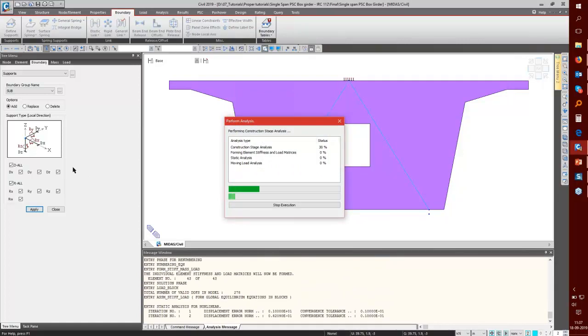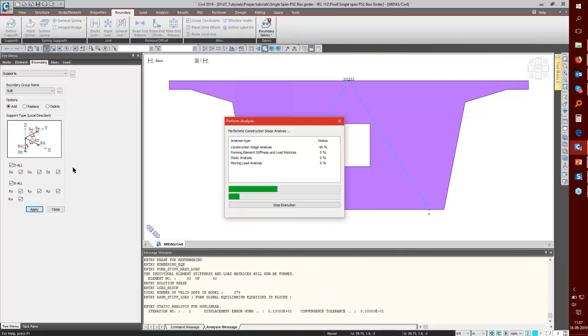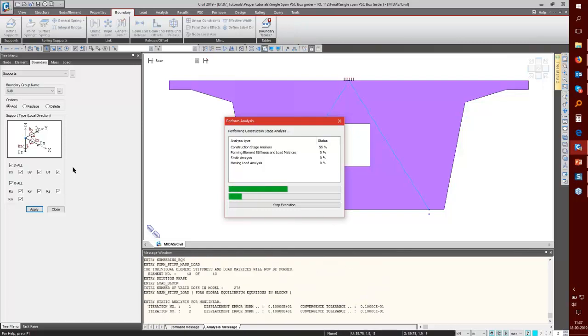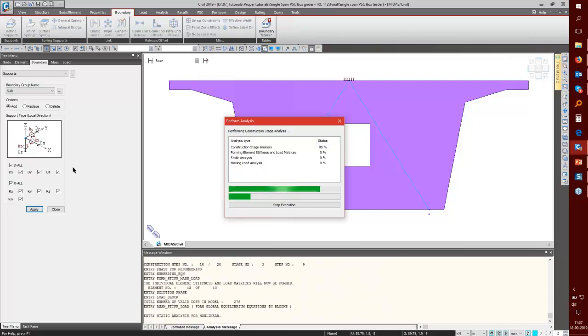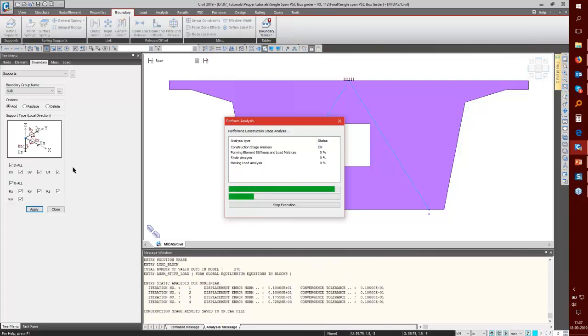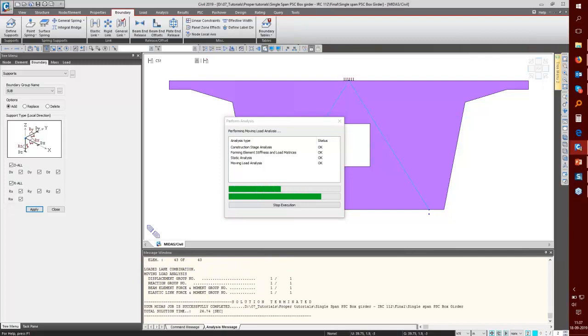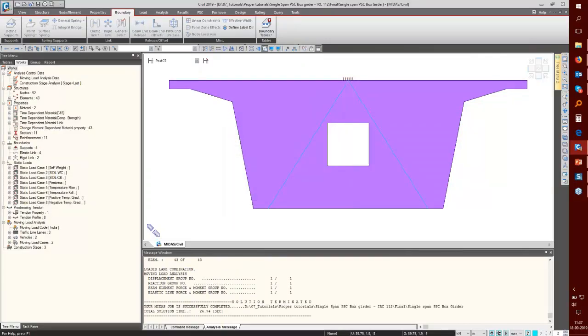Now, the third and final difference is, as we all know, the behavior of the structure, or the force attraction of different components, is based on the stiffness value of the structure itself. So let us say I have continuous beams and there are two beams. The beam which is stiffer will attract more forces than the beam which is less stiff.